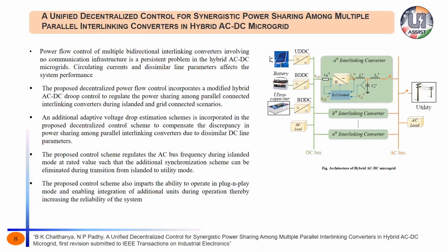One thing I would like to say is the DC line resistance has a large impact on the voltage regulation done by the battery. The very popular solution for this is using virtual impedance techniques, or regulating the bus voltage by means of some secondary control.